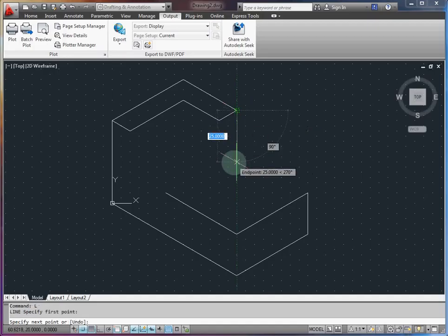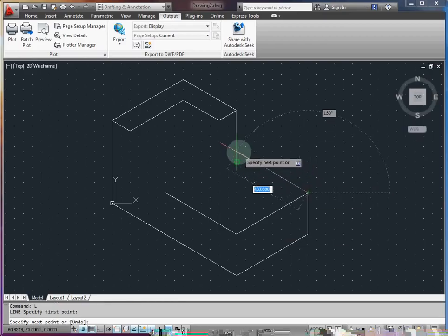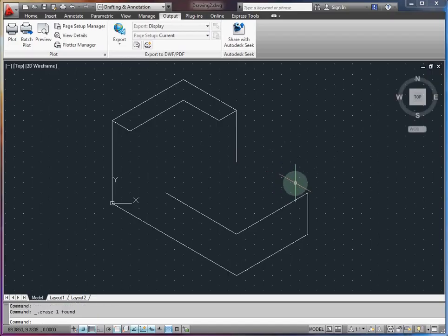Now I'm going to fill in the vertical lines at the outline, and you can see I went ever so slightly overboard there. So I'm just going to draw that correctly. What's actually happening here is I'm trying to draw to this point, but it O-snaps me to the bottom. So there's a couple of fixes here.